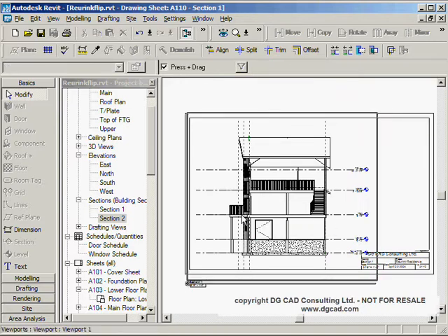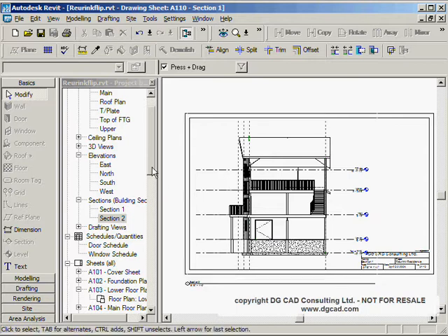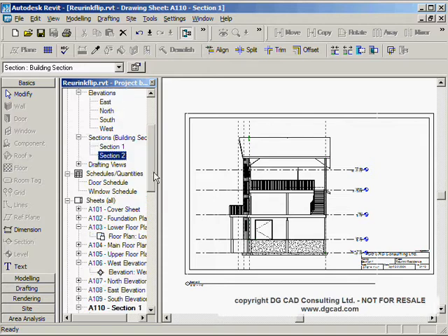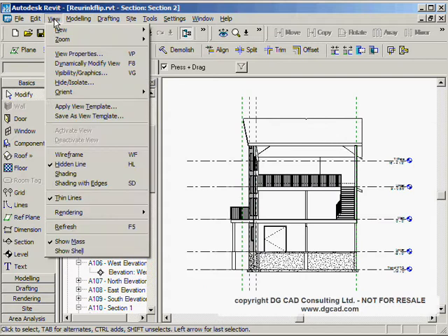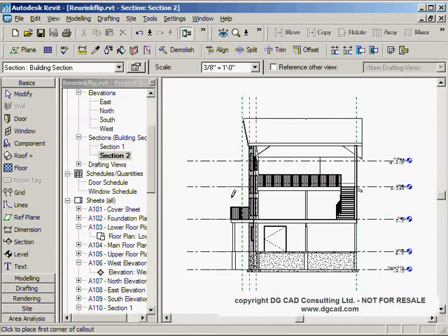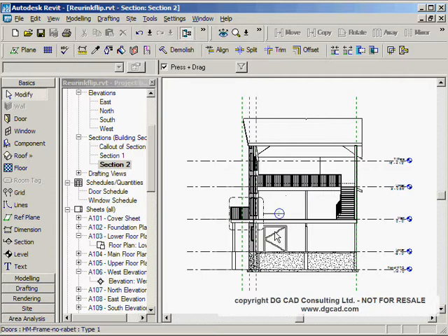And then you've got your section back. If you had a section, the section has been placed onto this sheet, which is a process outside of this lesson, but is a good demonstration of how you might have to take this section and drag it back down into this sheet. As well, if we go to this section and we had a new call out view, that call out wouldn't have come through properly in our mirror either.